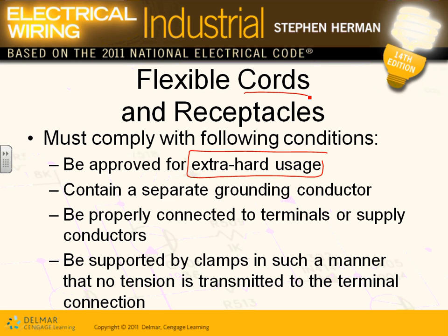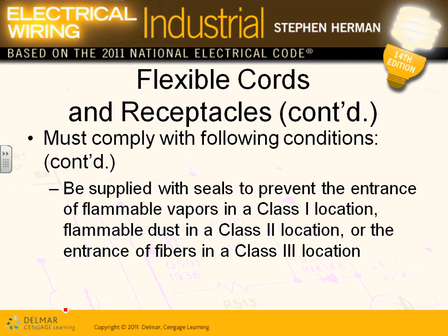Look at this. I need a separate equipment grounding conductor inside this cable. It must be properly connected to terminals with the proper connections and terminations. It must be supported by clamps in a manner that the tension does not transmit into the terminals of the connections. That way you use the mesh so it doesn't transfer the tension of the cord, the weight, onto your connections.